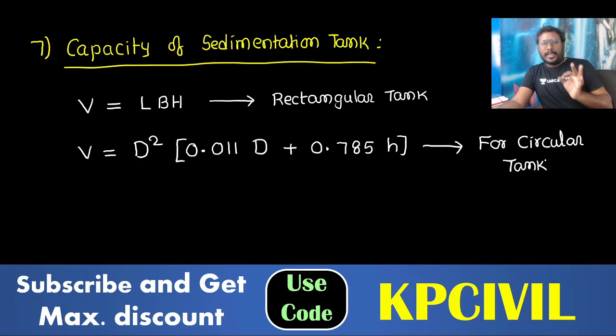Volume is equal to D square into 0.011D plus 0.785H. This is a specially designed formula for the sedimentation tank. So we got everything: surface area, volume, length, width, depth and diameter.